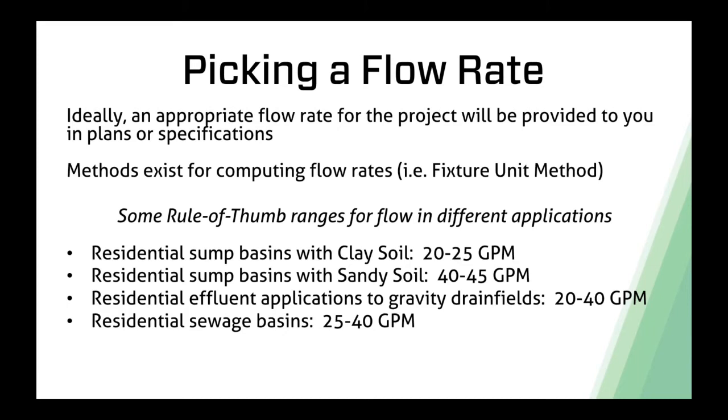These again are just rules of thumb. The reason that it goes up is if you have sandy soil around that property, water moves far more easily through sand than it does through clay, and so it can travel more rapidly. If it's raining hard outside, that water can move through the sand and get to your sump basin much more quickly. So you may have to have a higher flow rate in your sump basin to keep up.